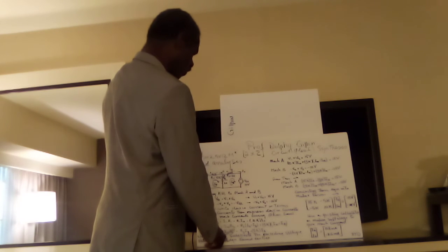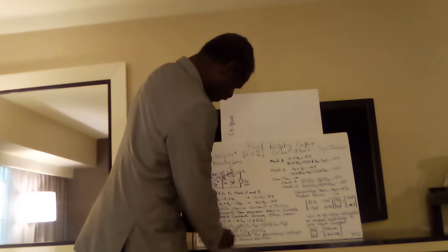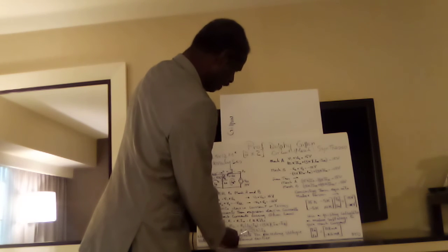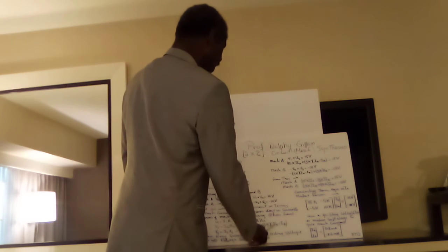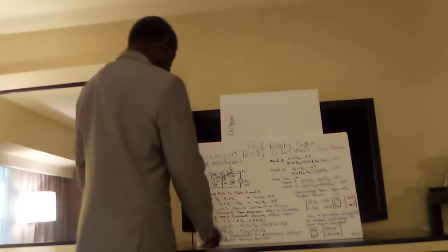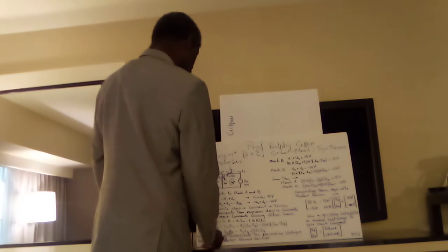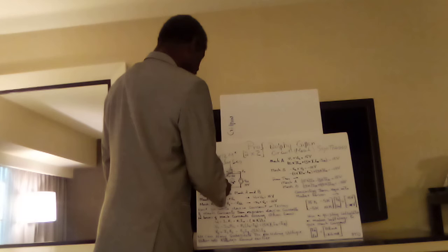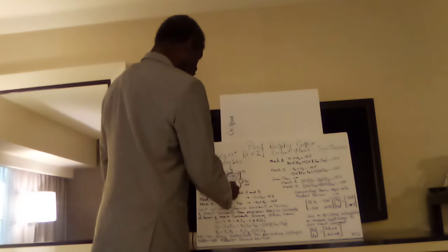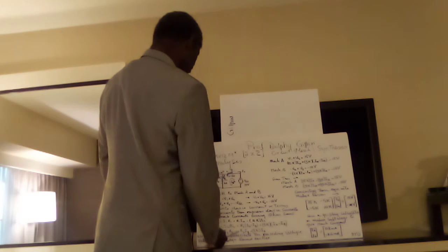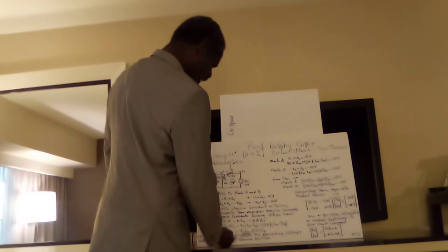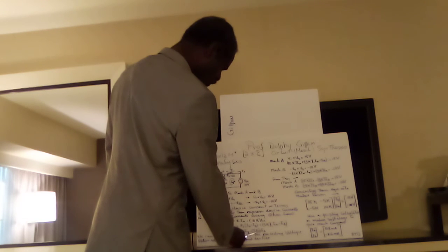And so now that's equal to R2 times IA minus IB, which is equal to 5 kilo ohms times IA minus IB. And similarly, V3 is equal to I3 R3. And here we have V3, and this is I3 going like so. So V3 is equal to I3 R3, and that's equal to R3 times IB, which is 5 kilo ohms times IB.